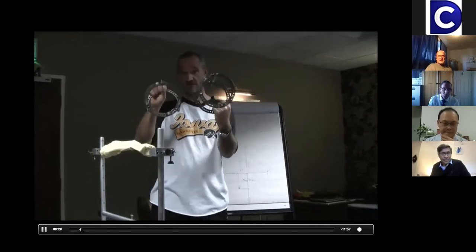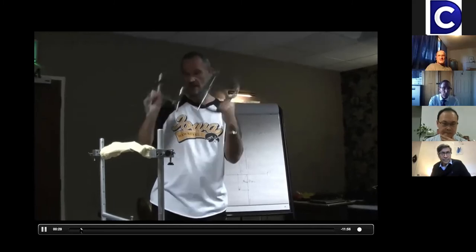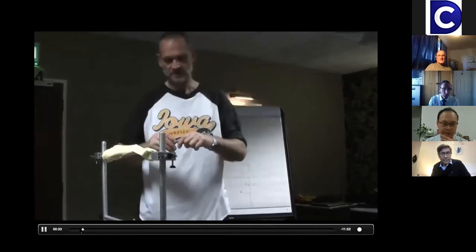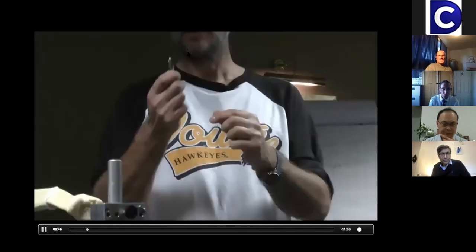The next thing you need to think about is how you're going to connect your rods together, how you're going to connect your couples together. So this is just a demonstration of the hinges I tend to use. I know you can buy pre-made hinges and special hinges, but I still build all of mine out of threaded rod, a high-profile female, a nut to lock the female onto the rod, and then another nut lower down the rod, which is what's going to be used to adjust that. And obviously, you need at least 4 of those because you get 2 pairs of hinges.